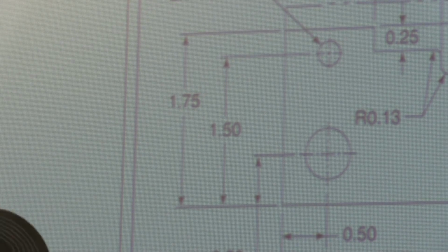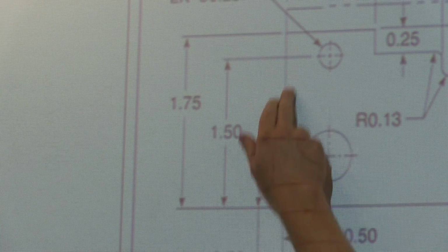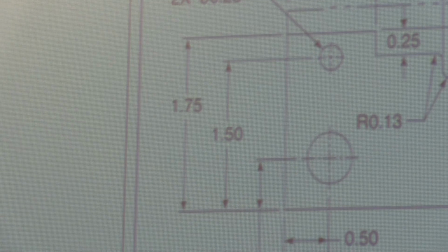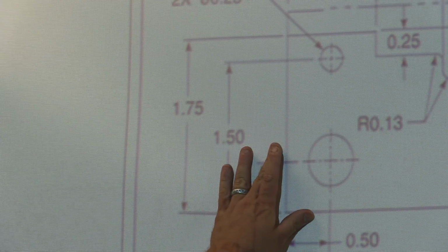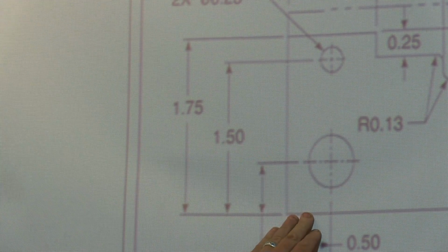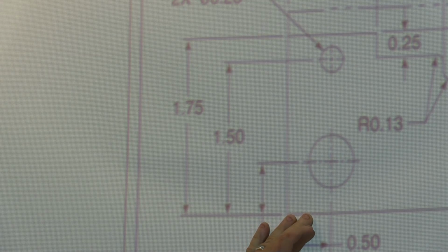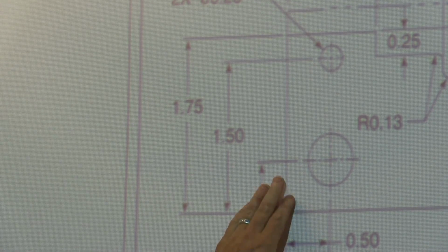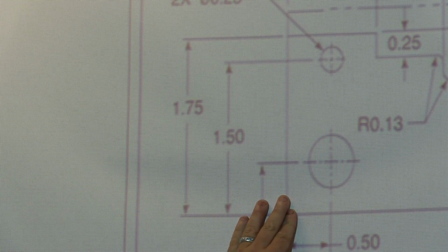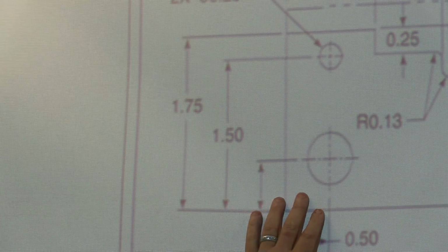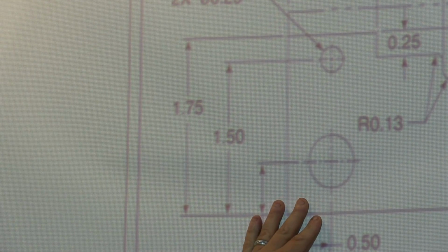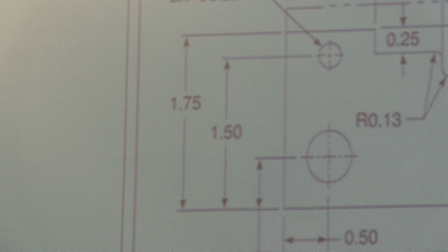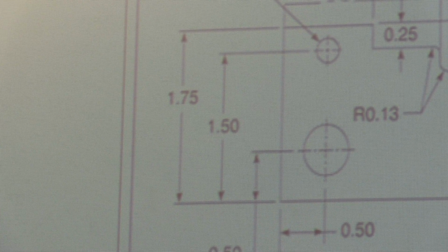We would want to square off, make sure that this is perpendicular here, and then from there, this is our measurement point. Okay, this is our datum lines, is where we would start. Because we know that these are machined correctly to begin with, then we can start doing the rest of our layout in that fashion. Correct, Dan? Correct. Okay. So if we look at it on the right-hand side,